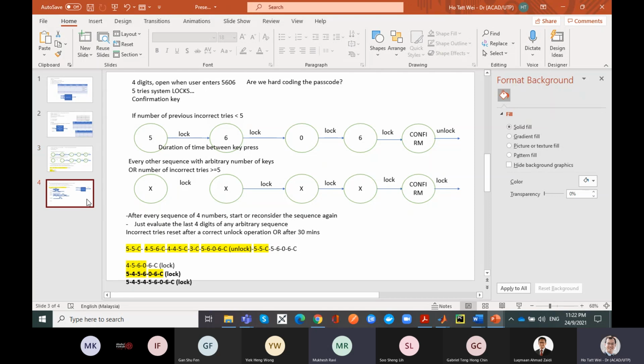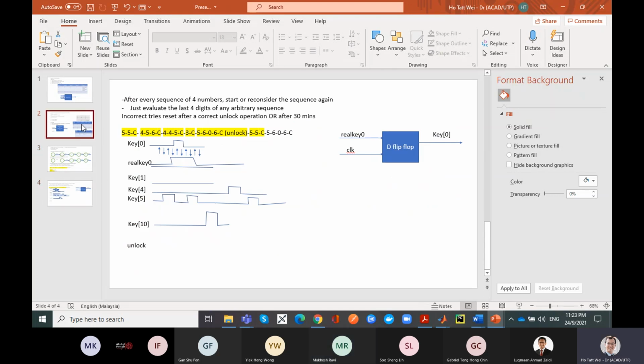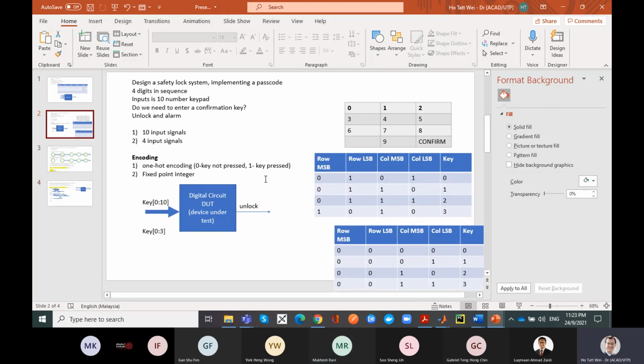Okay, so complete design specification. You have to start every design with a complete specification. Draw a black box. Give the complete listing of what the inputs are, how many bit width and all that, and what the outputs are. Define and name every single input pin. Define the logic level. What does logic 0 mean? What does logic 1 mean?